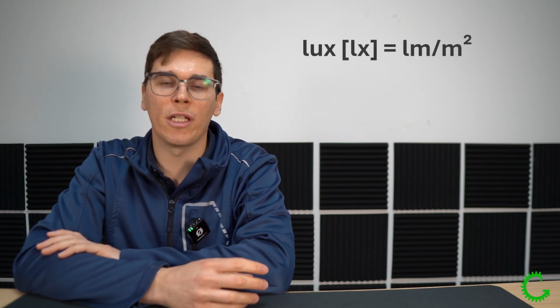Let's move to illuminance, which is measured in lux and is the ratio between the luminous flux, so lumen, divided by the surface of the object or surface to light, so square meters, and measures the quantity of light we see from the surface, let's say. It's measured with a tool called luxmeter, and is a final goal of our lighting system.